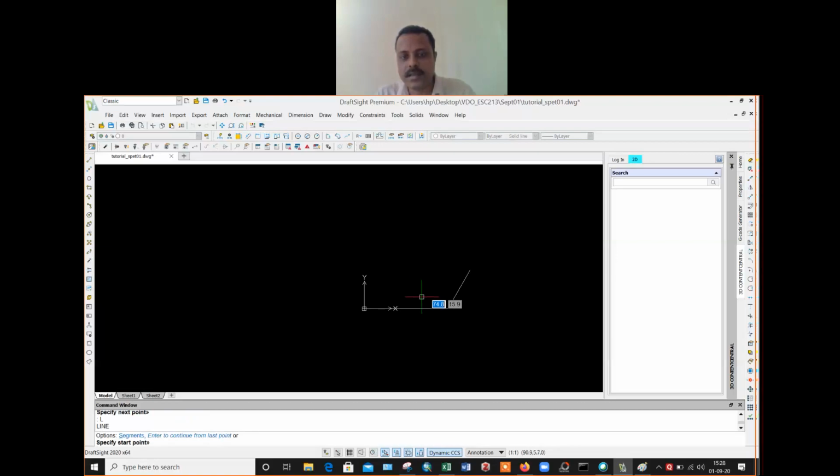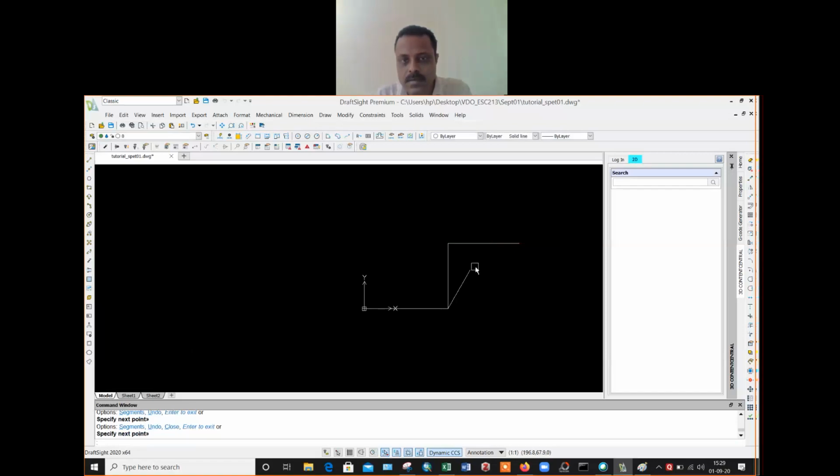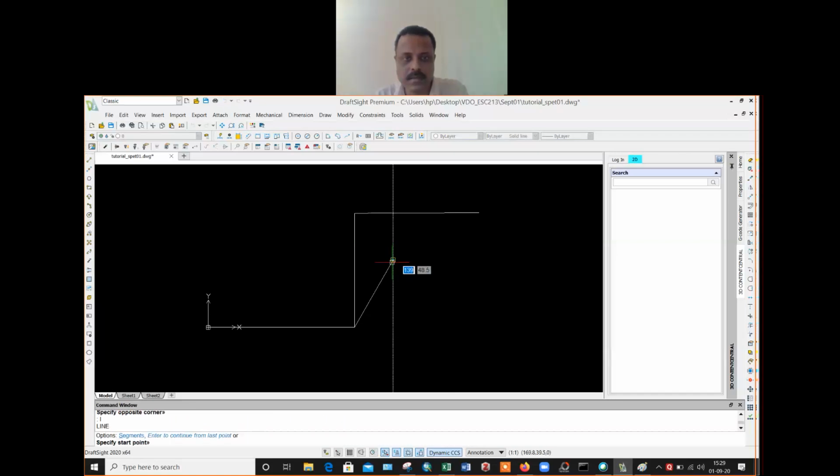I can say line, then @85<90. And then if I press F8, up to here, this is 85. I say line from here.